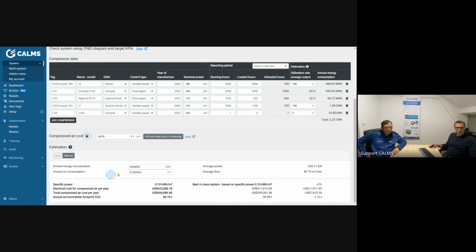Now the question: is this already a good number? What is this? It's close to zero. That's almost nothing. Correct, but 19 cents. But look here. Oh my God! This is the approximate number of cubic meters that you are consuming, so we are talking in millions. So you have to multiply this number by those millions, and this below is just a rough estimation. So in 1 year, we estimate it's almost $400,000 for compressed air. Oh, it's not nothing. It's quite a big number. That is a lot of paychecks. No, it's not coming out of my paycheck, that's for sure.